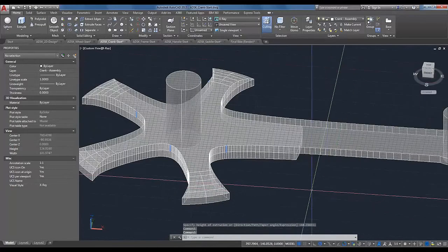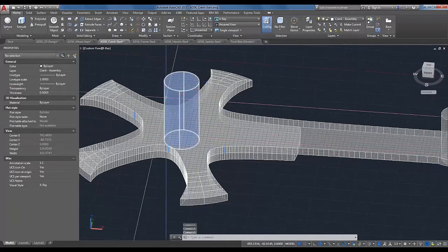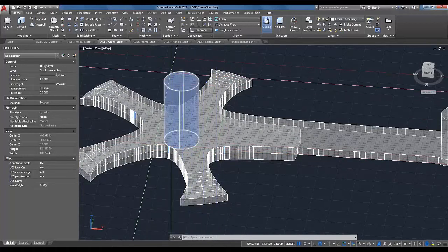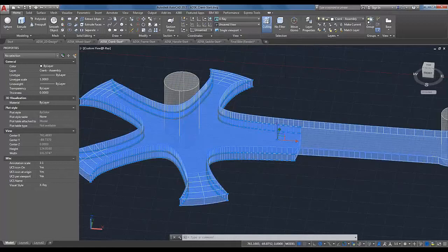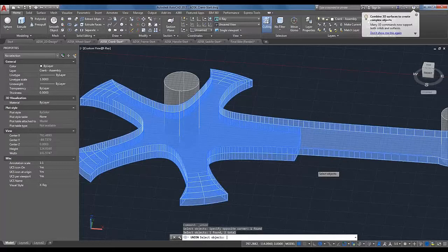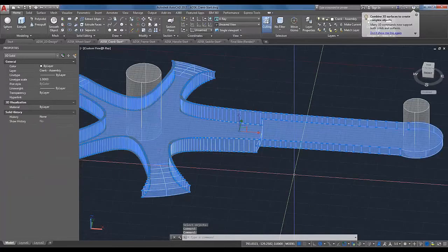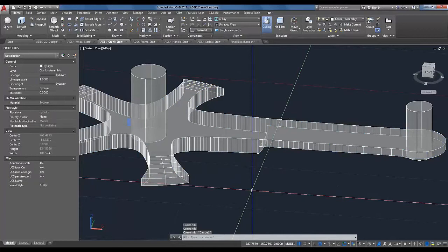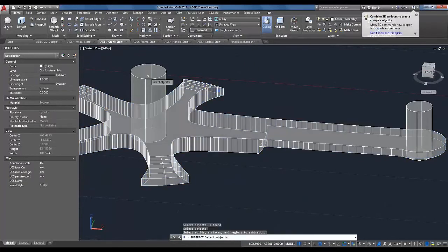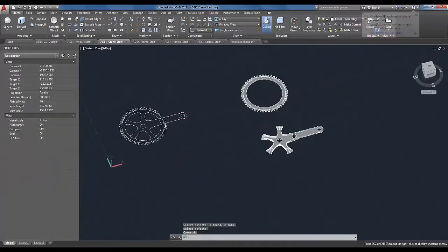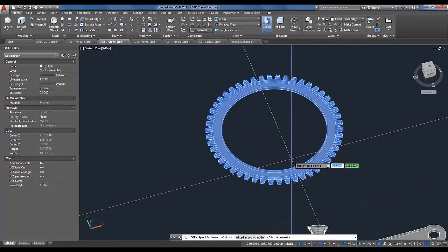And so I don't have to keep doing this routine over and over again in this section, because I have two separate 3D solids that have the cylinder protruding through it, I'm actually going to union these guys first, so I only do it once. There we go. So now it's one piece. But had I done that before, I wouldn't have been able to easily remove that lower section over here. But now, quickly get rid of these guys. Starting to look pretty cool. Going to copy this guy over.